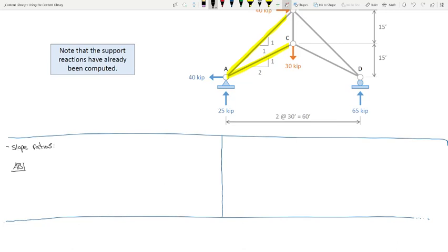Member AB, we have this sort of slope ratio that's written kind of like this. We have a right triangle like that. And we're told that member AB is at a 1-to-1 slope ratio. So if this is 1-to-1, what's the hypotenuse? Ooh. Square root of 2. This is the square root of 2, right? This is 45, 45, 90. Now, up until now, we haven't actually looked at the hypotenuse, but we're going to need to do that when we write our equations of equilibrium. So what I would tell you is that the only time that you're looking at the hypotenuse in a fashion like this is when you're looking at two equations and two unknowns.